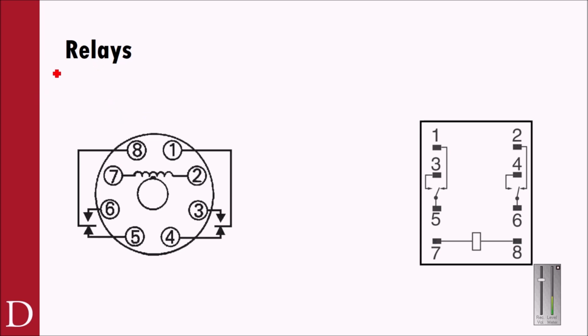It's very important for you to be able to look at a schematic diagram, whether that's a schematic diagram of a relay on a technical data sheet, or the schematic diagram of an elevator control circuit or something like that. And really what I'm looking for when it comes to relays is the ability to identify some key components. So if I look at this one as an example, this is a standard ice cube relay, has a round base on it. And it's got sets of contacts. A coil. It's going to have a set of normally open contacts and a set of normally closed contacts.